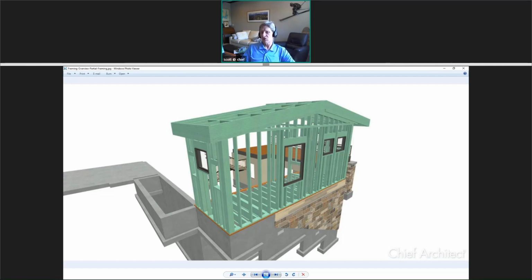So if you removed your roof from the as-built, then run the materials list, you're not going to get the materials list for anything that wouldn't be new. You can set up layers, and there is a way to generate the materials list from layers. We may be going away from that in the future. I'm not usually one to encourage that, but you can approach it. But maybe consider just removing your roof off of your as-built if you want just the materials for the new roof. Al, would you add anything with that?